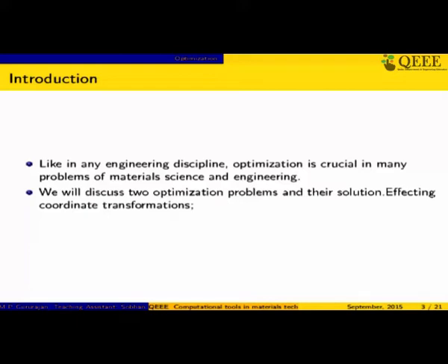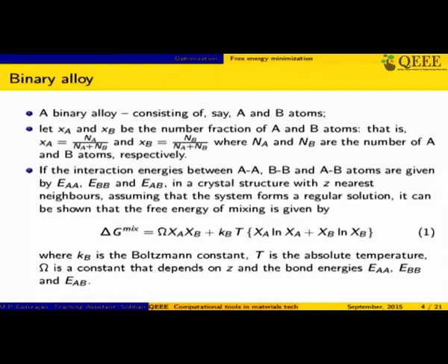The most important optimization problem that one comes across is basically free energy minimization. In systems in which temperature is constant, it is easier to do a free energy minimization rather than an entropy maximization. But if temperatures are changing, in non-isothermal processes, you have to do entropy maximization.